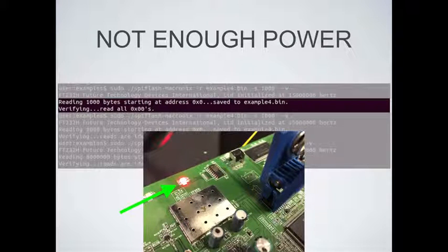Another thing that could happen is you don't have enough power. When you're reading stuff off of an embedded system, or reading from memory, the board is not going to be powered. You're actually gaining power from the VCC of the cable from your USB interface, and there shouldn't be power to the board at all when you're doing this type of work. But if you look here, there is actually an LED on when I have this attached to the board.